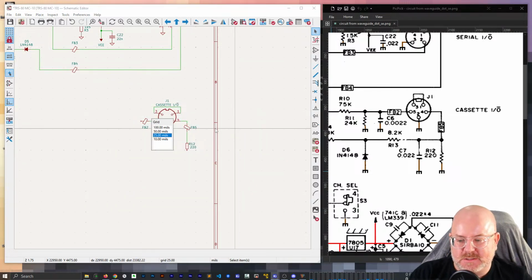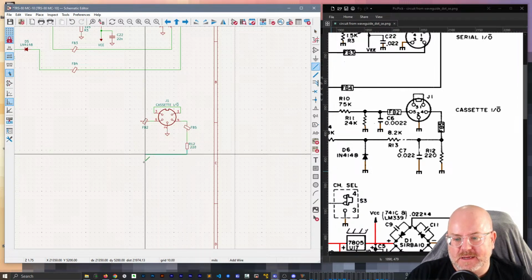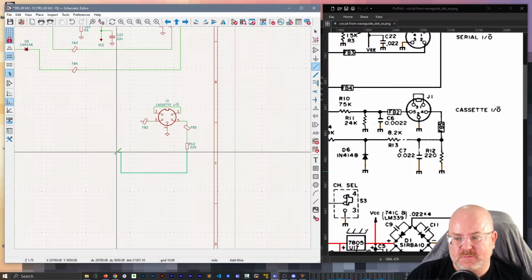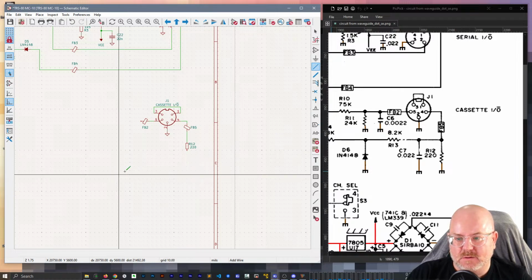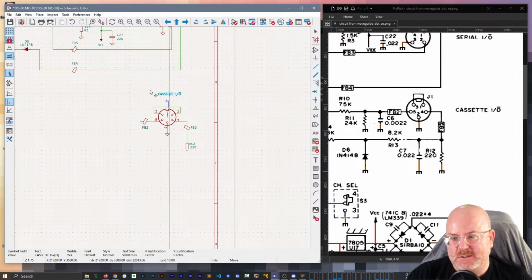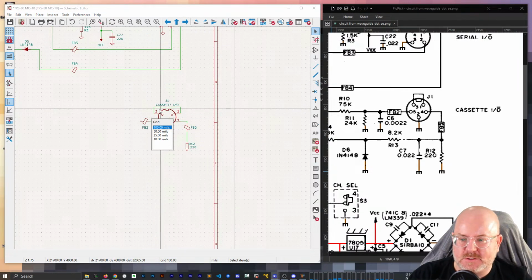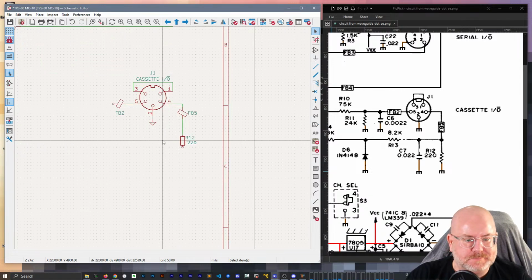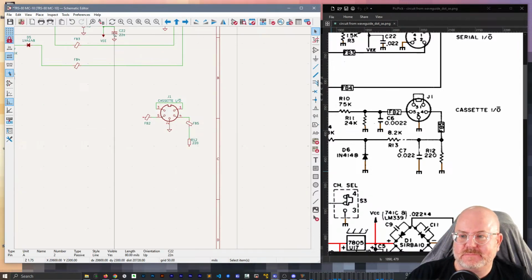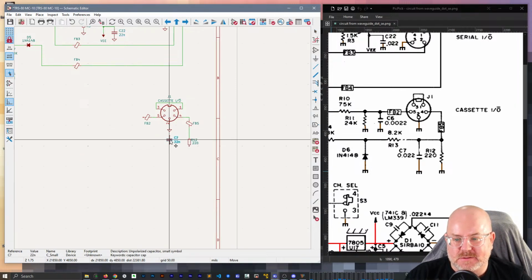So even if I set this to 10 mil and then try to draw a wire, I'm still locked to a wider grid. But if I go and move text, it's a much finer grid. It can basically go anywhere, which is great. It just solves the problem. And if you don't like it, turn it off. But I think that would be silly.